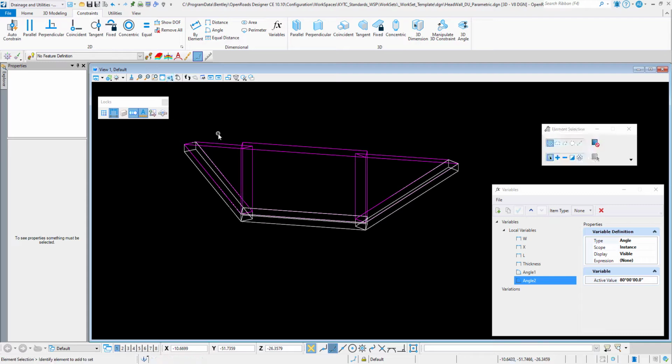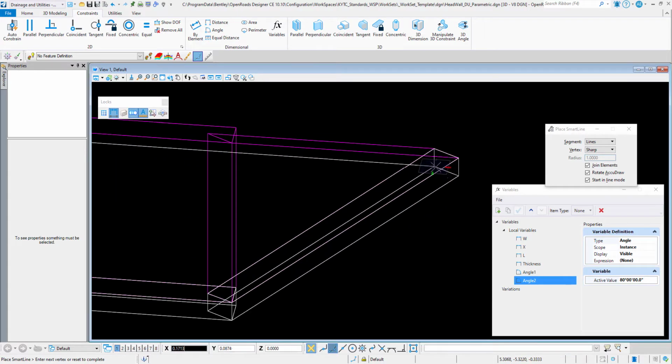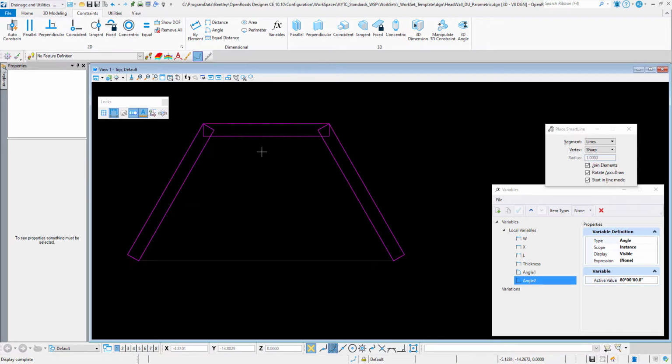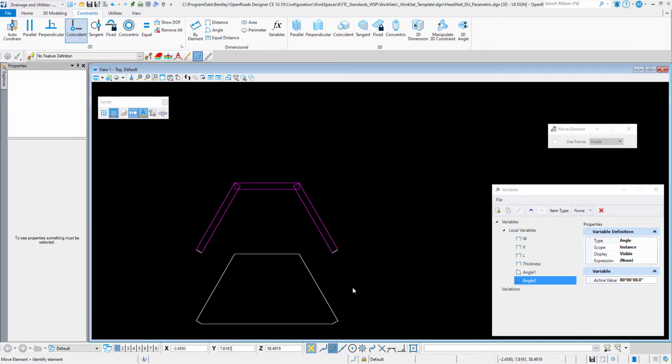Now, what I want to focus on now is that bottom shape. So now that I have my collar, it sits on a flat bottom shape. There might have been better ways to draw this, but this just happens to be the way that I did it. A little bit more efficient ways are definitely to be had. So just like with the other collar, I traced over some of these points and I'm moving it off to the side. Again, applying very similar constraints. My back wall value, my lengths, my angle.